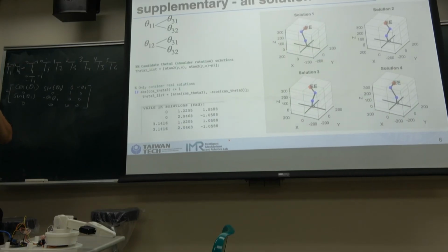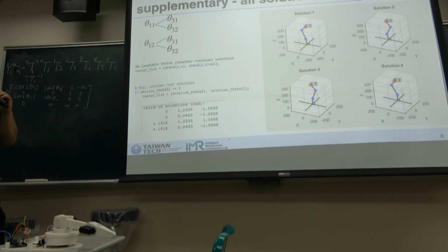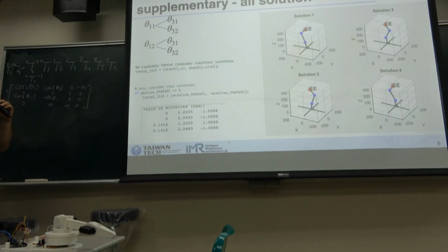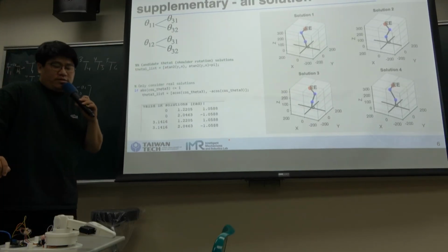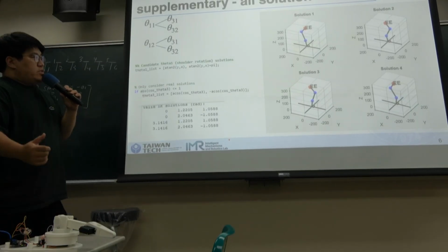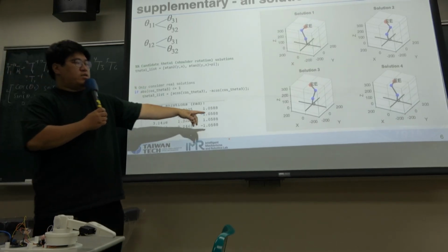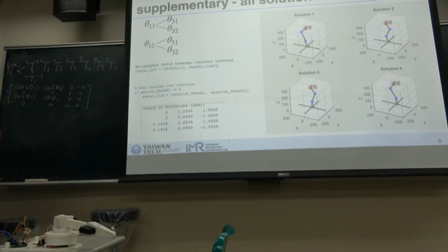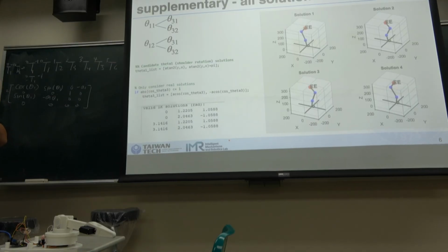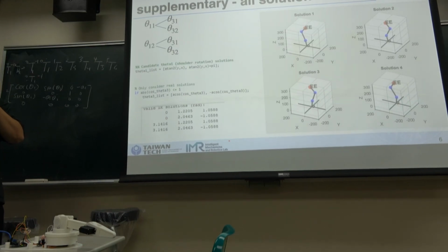And then second, today we are going to find only one solution, but if you want to find all of the solutions, you can use this kind of trick. In our case, only the first theta will change the orientation on the xy plane, right? So you only have two theta. One is the positive one, and then one is plus pi, plus 180 degrees. You will have a backward solution, right? So it's an easy one.